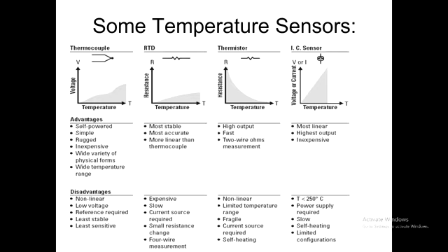Okay, well that's basically what we're talking about here, and the characteristics are that it's very linear, its range is somewhat restricted. It's got some thermal mass, so it takes time to warm up, and that thermal mass will incur what we call insertion loss, because in measuring, because it's got thermal mass, it'll take heat away from that which you are measuring, and that which you are measuring will cool down a bit as a consequence. So that's something to bear in mind.